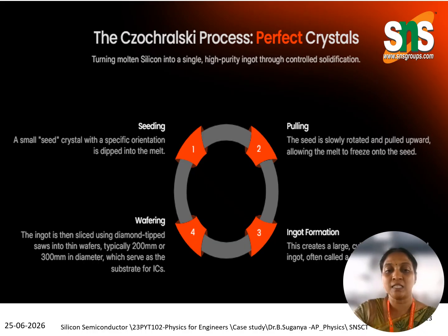And the third process is wafering. The ingot is then sliced using diamond-tipped saws into wafers, typically 150 millimeter, 200 millimeter or 300 millimeter in diameter, which serve as the substrate for ICs. And ingot formation creates a large crystal structure.